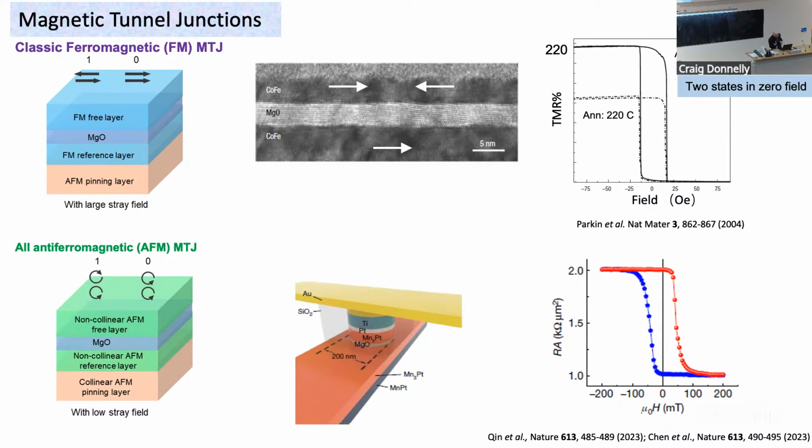And these Kagome systems then, in 2 papers published in Nature in 2023 by a group in China and Japan, they demonstrated the first tunneling junctions which used these chiral anti-ferromagnetic layers, basically a conventional structure where you replace the ferromagnetic layers by these chiral anti-ferromagnetic layers. And one group reported at room temperature a change in resistance of about 100%. The other group, more consistent with our own work, only 2%. So this, nevertheless, is a very interesting ongoing topic.